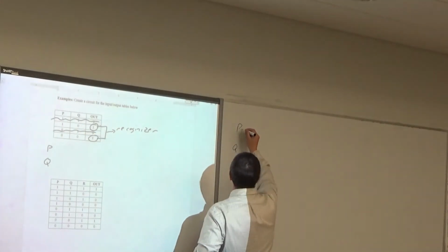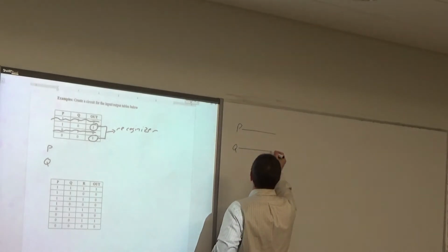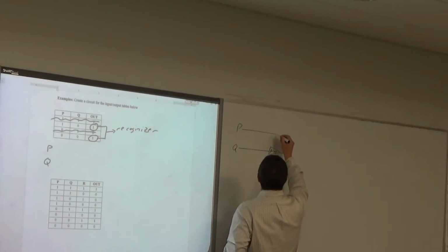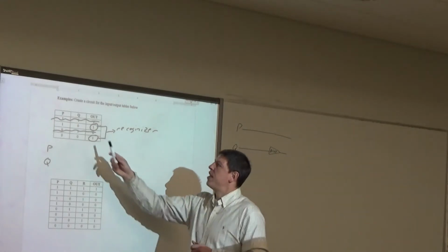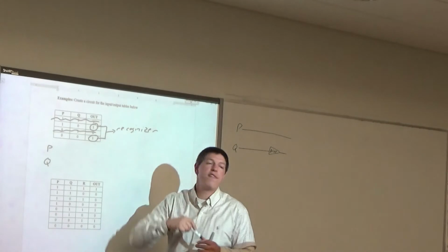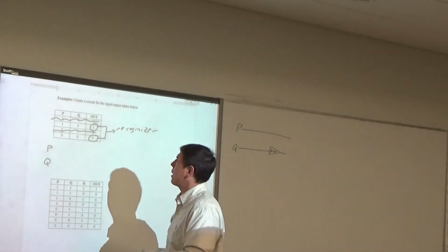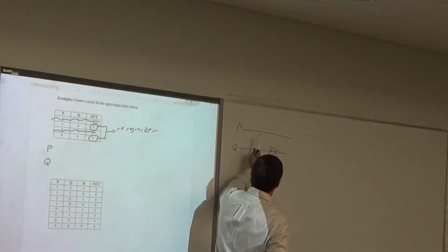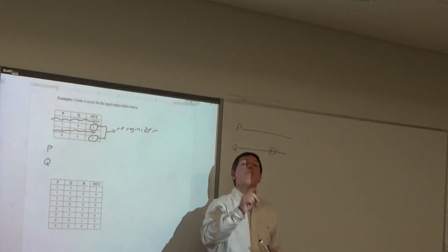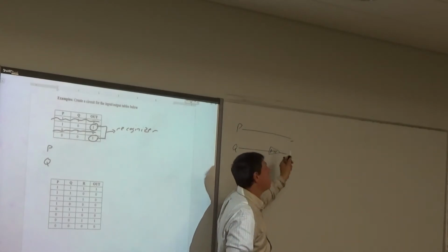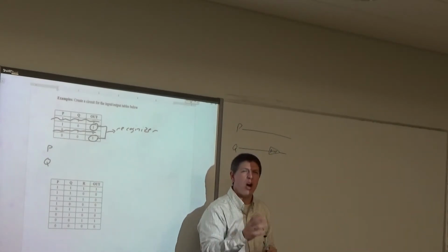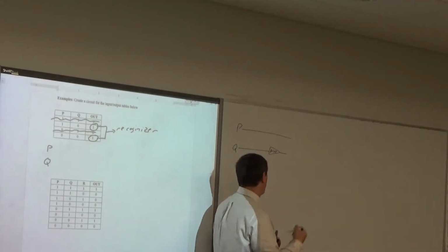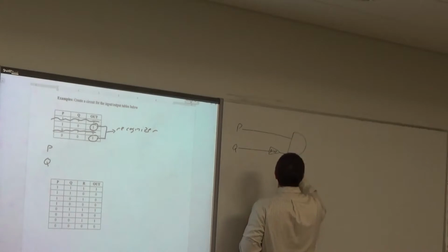So here's what I'm going to do. P is true, and I want Q to be false. So basically, if it has a 0, I'm just going to affix a not to that. Okay? And think about it, guys. If I throw 1, 0 through this, that's going to end up being true, provided that these two are connected with what digital logic circuit? Not an OR, but an AND, right? They have to both be true. Okay, so I'm going to connect these with an AND.